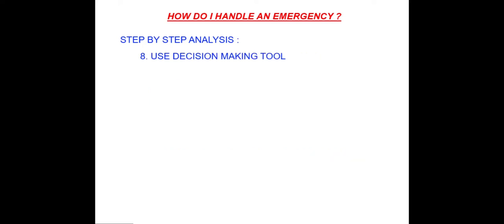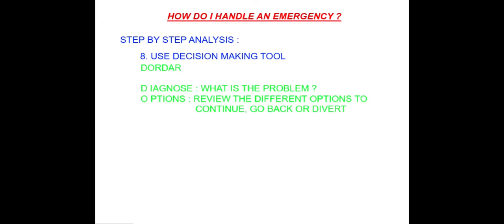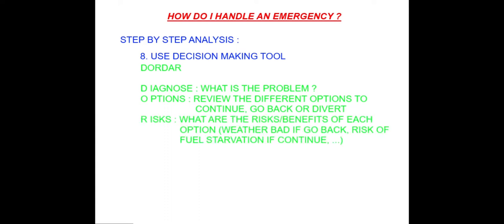Step number 8. Use decision-making tool. DORDAR. D for diagnose, what is the problem? O for options, review the different options to continue, go back, or divert to an alternate. R for risks, what are the risks, benefits, of each option?